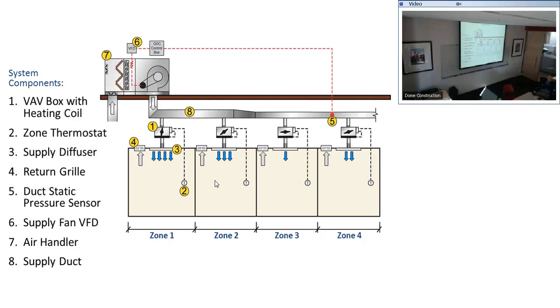Because the only way you get heat loss is if you evaporate it or you're using a compressor to pull the heat out of the system. Cooling coils in an air handler produce water because of taking the air moving across the coil, condensing water out of the air.